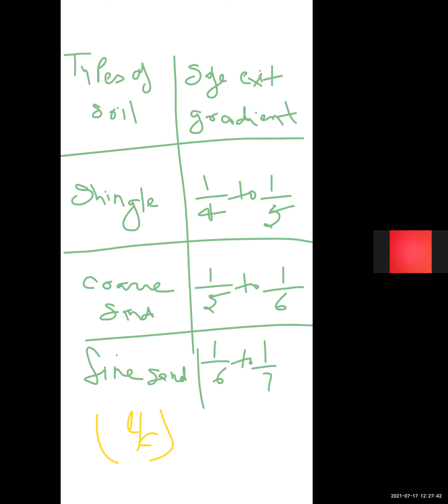So Khosla's method of independent variables is used for the determination of pressure and exit gradient for seepage below a weir or barrage. Also in Khosla's theory, we have to apply some corrections, that is correction for mutual interference of piles, correction for thickness of floors, and correction for slope of floor.